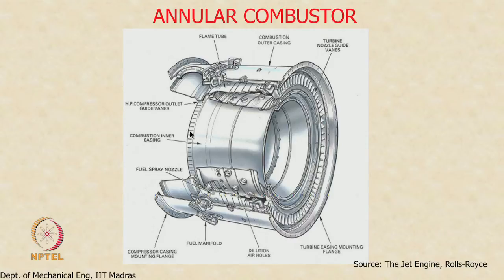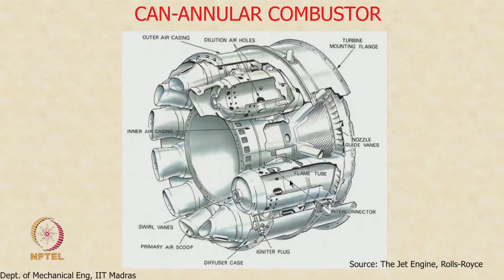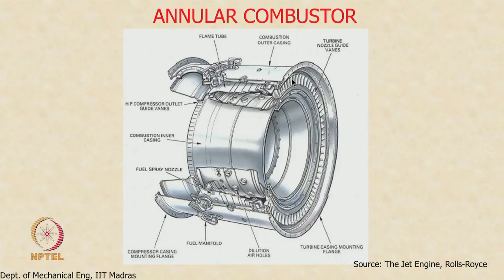So, the high pressure air comes in here through these guide vanes, they are directed properly here, and then they go out here. Again you have these guide vanes which directly feed this hot air into the high pressure turbine blade. The shaft sits here. Notice that this is the only portion where the hot air comes out. Okay. So, the hot air comes out only through this passage into the turbine blade, right. So, you must keep that in mind.